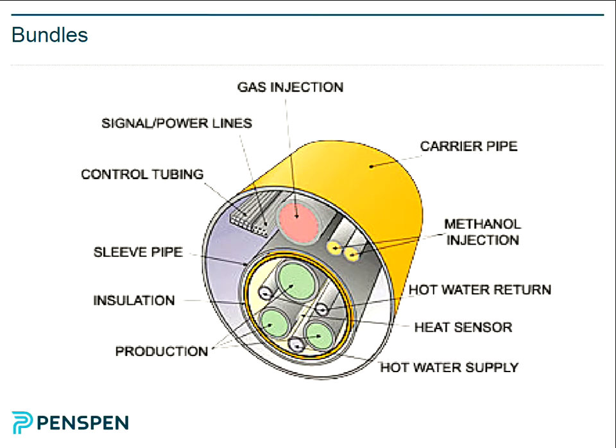A lot of pipelines in the North Sea were actually installed using bundles, and in the Gulf of Mexico as well. Typically in the North Sea they use this mid-depth tow technique, where it's towed hanging in the mid-depth of the water column. In the Gulf of Mexico they use another technique they call the bottom tow. They actually drag it along the seabed to where they want it. That's been used. So this is a bundle.